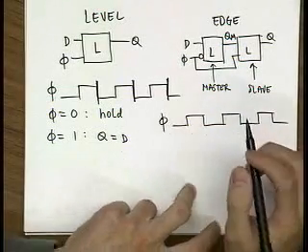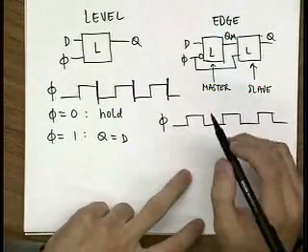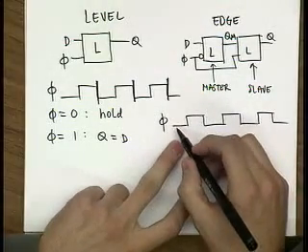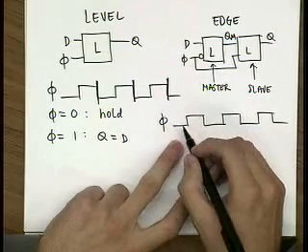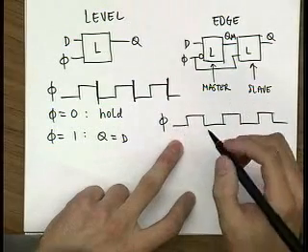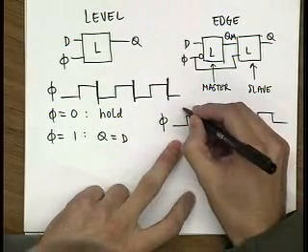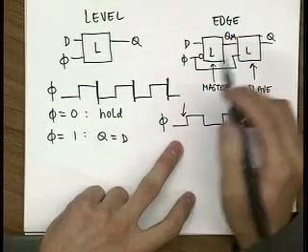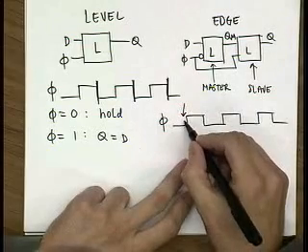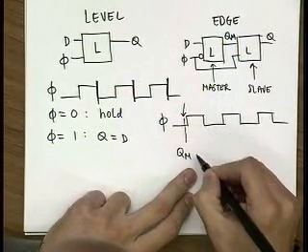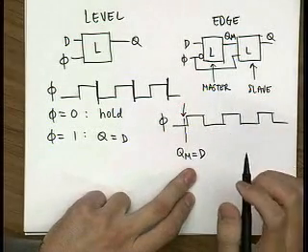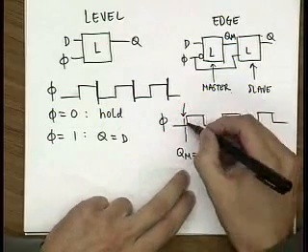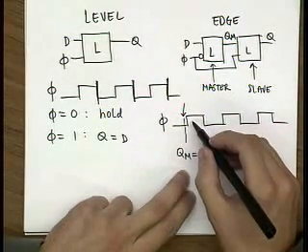So what this does is then, if this is clock phi, then when the master latch is transparent, clock is low, right? So at the rising edge, here's the last chance for your master latch to copy the data from the input. So at this point, QM is equal to D. After that, your slave latch becomes transparent.